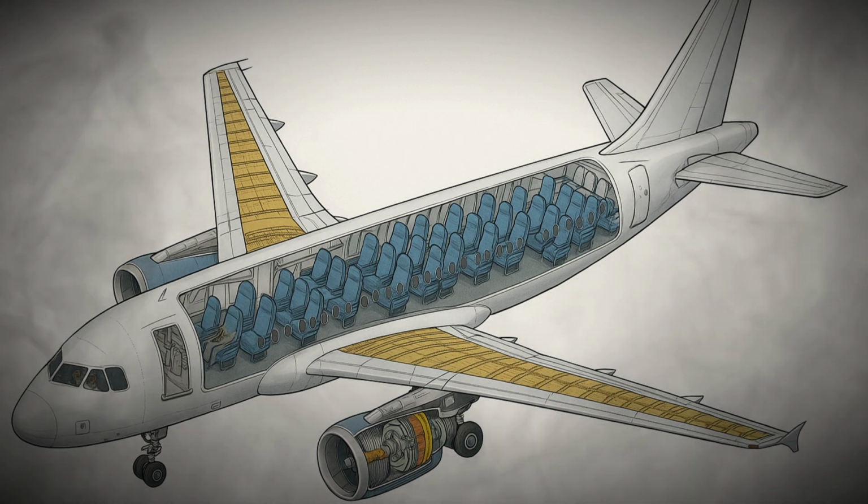Takeoff begins with taxiing the airplane from the gate or parking area to the runway, guided by ground control. Once cleared for departure, the airplane aligns with the centerline of the runway, and the pilot advances the throttles to bring the engines to takeoff power. As thrust increases, the airplane accelerates rapidly down the runway, with airspeed indicators rising steadily. During this acceleration, pilots monitor critical speeds known as V-speeds.